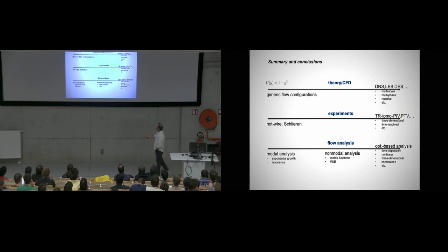A good step was already sort of to throw back in that finite time horizon of a stability and redefine stability and abandon the Lyapunov concept, which doesn't work so well for fluid mechanics because we have limited timescales. And now go one more step and throw in that optimization-based analysis, realizing that these two things are just special cases. So let's go back to the general case that meshes up with all the things we do in experiments and theory, and then do the stability analysis based on the optimization. So thanks for your attention.